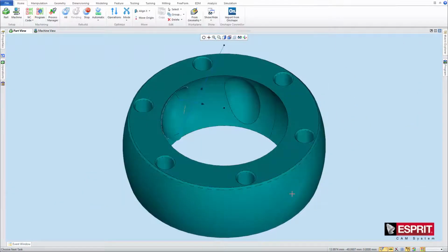The next example illustrates the vector field on drive surface orientation strategy, available in the cases of project parametric and project spiral patterns. This strategy uses a drive surface to define the vector domain and the influence distance in accordance with the vector attract mode setting. First, we will see how the global attract mode affects tool axis orientation.